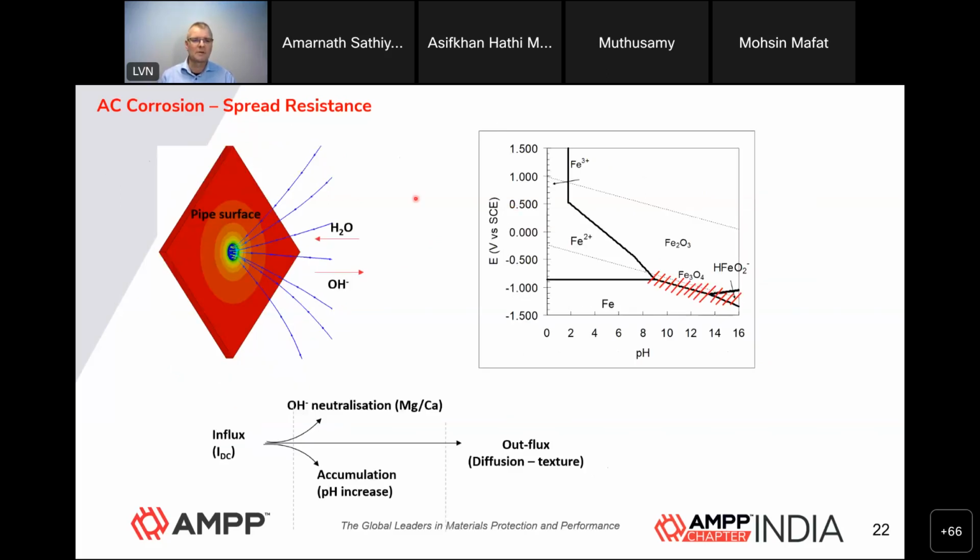It's very simple. Consider your pipe surface with a coating fault, where you are applying cathodic protection, meaning you are typically reducing water molecules into alkalinity. Alkaline species like OH- carry a charge, and therefore they add to the conductivity of the soil very close to the coating defect.